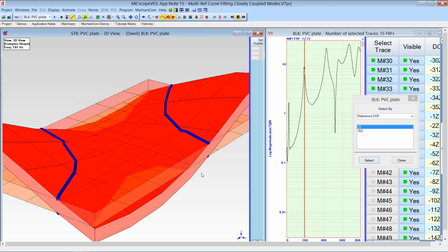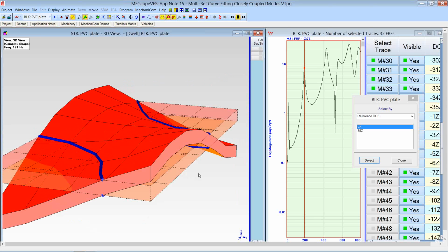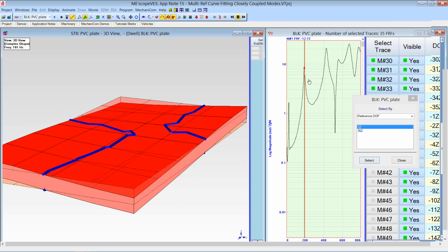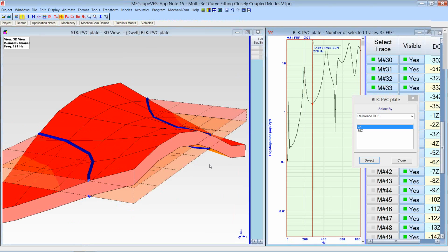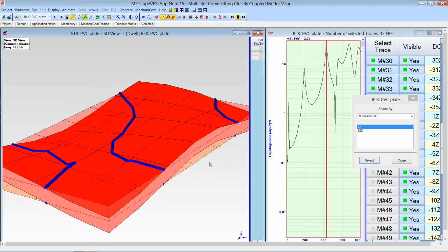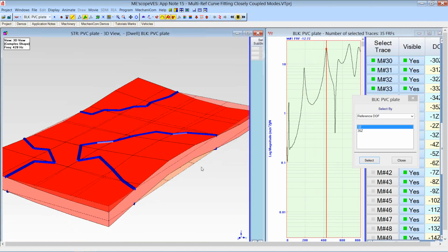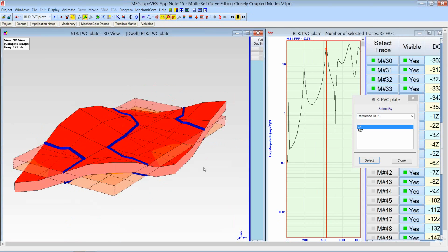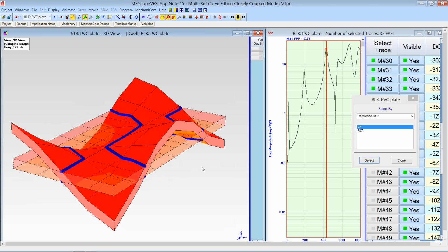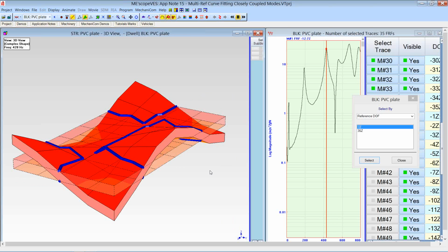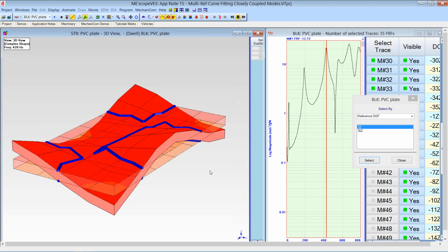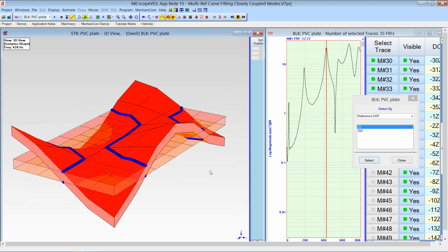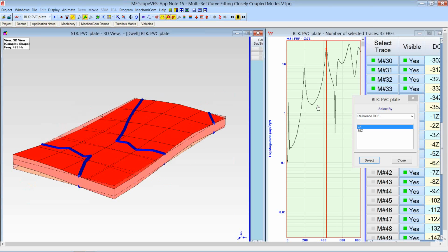Well, it's not clear what that is. It's not what I'd call a bending mode. It's not what I would call a torsion mode. Let's go up to the next peak. Now that clearly is a torsion mode. That's a twisting of the structure, but it's what I'd call second torsion. It's a higher frequency than what I would call first torsion or first twist of a simple structure like that. When you test a structure this simple with no boundary conditions other than the foam that it's sitting on, you expect to see a first bending and a first torsion mode. We're not seeing it in this data.